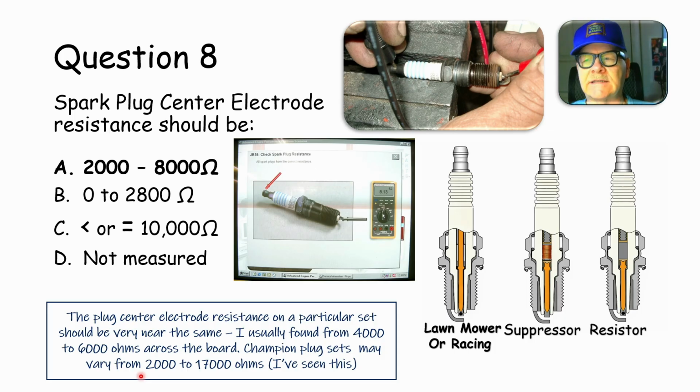I had also heard these guys at a Chrysler dealership way back in 1980, down in Port Arthur, Texas. One of them said that he had replaced the spark plugs in a car, because it came in there with a spark plug misfire. And after he replaced the plugs, it wouldn't start. And he knew he didn't do anything wrong, and so he put the original plugs back in it, it fired up. Put the new plugs in it, it wouldn't start, and they were Champions. And that was a Chrysler dealership, so I'm not hating on Champion plugs. I've used them before, and I never really thought a lot about it. But I'm telling you, measuring the center electrode is a valid test.